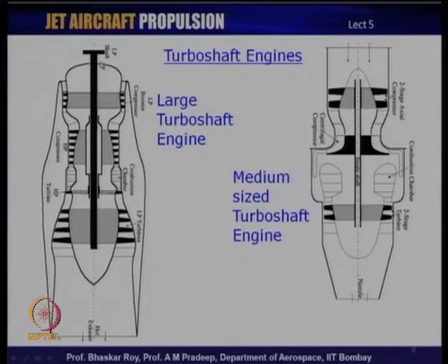At the end of this shaft, you would again have a gearbox, and you would have a big rotor which will be powered by this engine. Now, this is a straightforward turbo engine or a gas turbine engine, and this is a big turboshaft engine, which is a 2-spool engine. The inner spool is what is coming out to run the rotor. The outer spool runs the basic compressor turbine loop, creating the power or the power generating system.